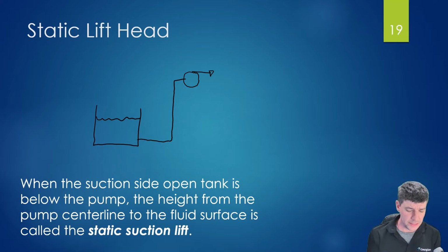So in this case, our static lift head would be from the center line of the pump down to the water level. And so that would be our measurement of our static lift head, that height measurement.